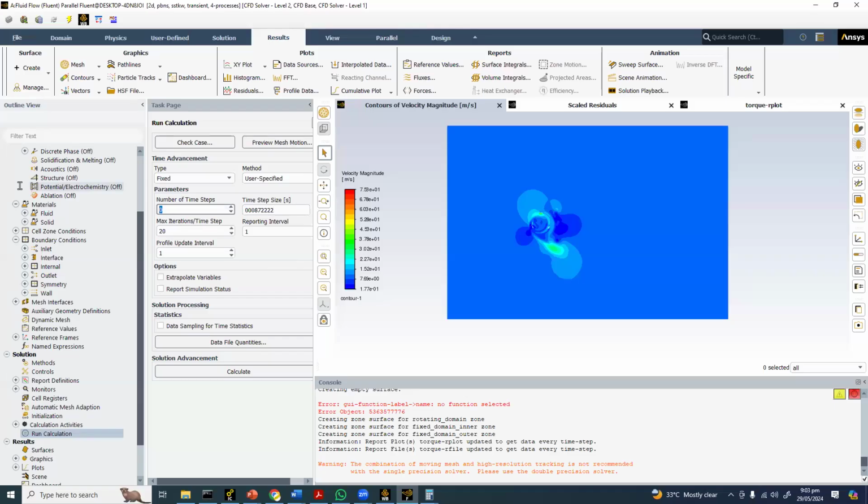The way we get the data from the wind turbine simulation is that we get the data for one revolution. Okay, so that is at least. So it should be for one revolution. So the people in the scientific community say that one revolution of data is required there. Okay, so to average out data, they say that you should be taking data for at least 5 cycles. Means that you will get the average data for the 5 cycles.